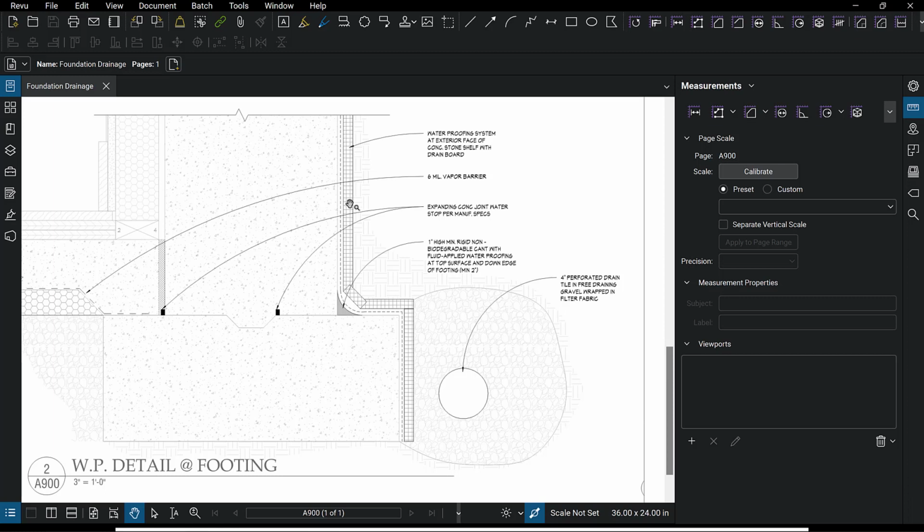If you think of the bubble wrap that you get with packaging, the drain board is a hard plastic version of it, but not so many bubbles, so there are spaces in between the bubbles. There's a filter on each side, so water goes through the filter fabric on one face, and the little bubbles create a path between the backing and the filter on the front, allowing the water to come down.